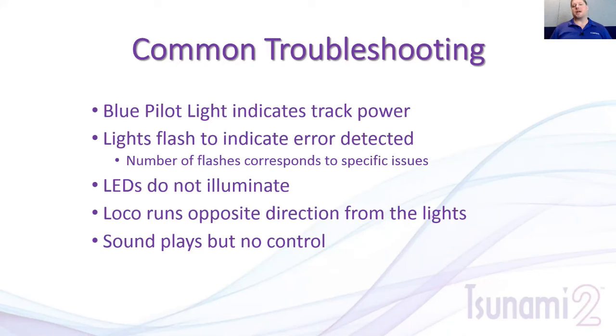So for example, if we have a locomotive with address 1000 and I've selected 100 here, no matter how much I will that locomotive to take the command, it's ignoring it because it's not sent to its address. So going back to what we talked about earlier with the programming track, you can always pick it up, put it on your isolated programming track, talk to the decoder, and make sure that it's responding and acknowledging programming commands by reading CV8. It should come back 141. Then you can go in and set an address or interrogate and find out what the address is.